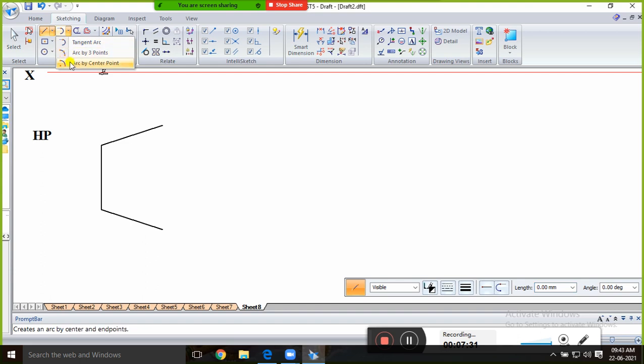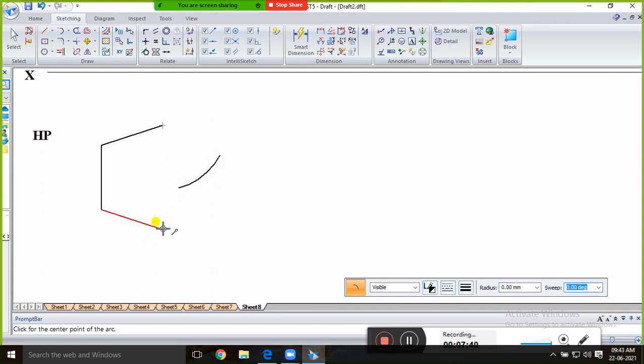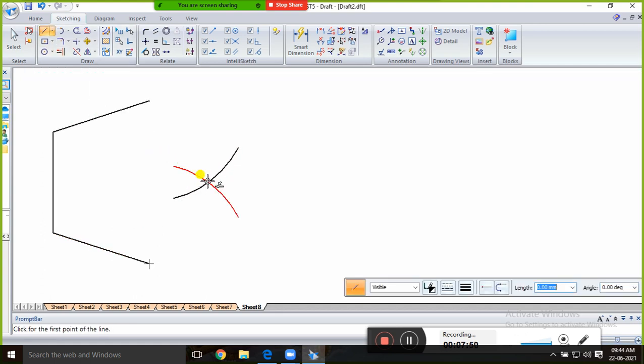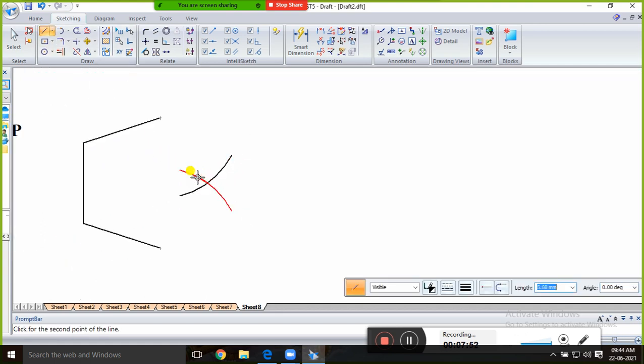And take this arc. Okay, so from your compass, radius is 25 mm, cut 25 mm, and from here place again, and take that 25 as the radius of the compass, and again cut another arc. Then take the line, okay, and place it here and join.